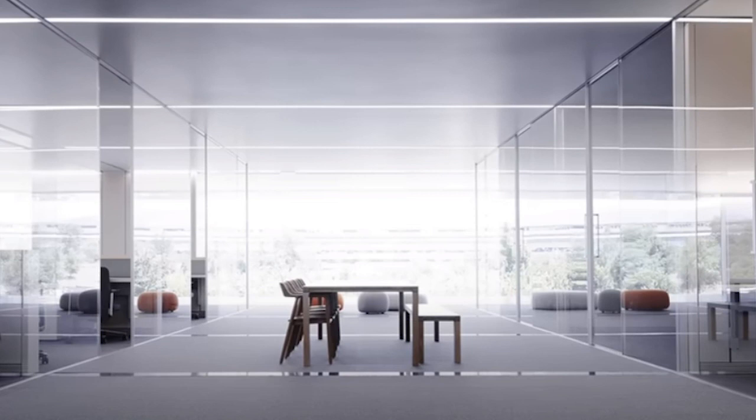Steve Jobs emphasized the openness of the space, with all the windows being floor-to-ceiling windows. The office space also emphasized this openness, so the method used was to notch the slabs so that the edge of the windows were not visible, creating an open feeling.